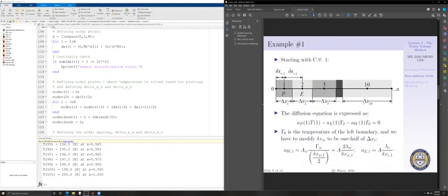And the easiest way for us to do that is if we have our nodes, all we have to do is subtract them. For instance, if we know delta x1, our cell center is going to be delta x1 divided by 2. So I'm going to take that value of node 1 less the value of node 0, and that specifies delta x1.